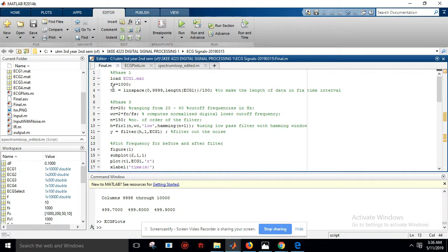The cutoff frequency we chose was 20 Hz, as we concluded in phase 1 that the typical ECG signal ranges from frequency of 0 to 20 Hz. To include all the information of a typical ECG signal, we used 20 Hz as the cutoff frequency, and we decided to use a filter order of 150 to improve the performance, to ensure that only the frequencies lower than 20 Hz are included after being filtered.